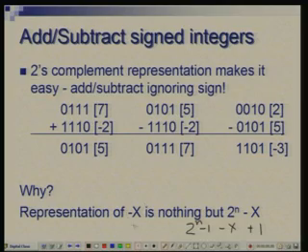So now what we are doing when we are adding and subtracting 2's complement numbers is that negative numbers are bringing an additional 2 raised to power n into the picture. So suppose you have several numbers x, y, z, w, 4 numbers to be added, some of them are negative, okay. So with each negative number we are carrying an extra 2 raised to power n, okay. So if you are adding a series of numbers, some positive, some negative, we would be carrying a few extra 2 raised to power n's, which will all go out as superfluous carry on the left side, okay, and the result we get is a correct value.